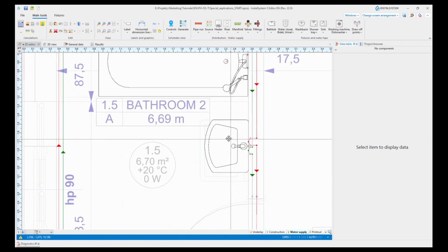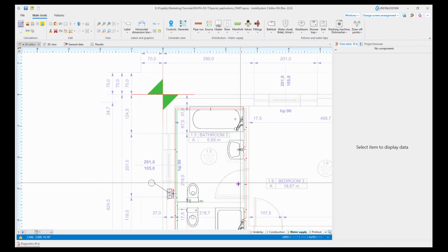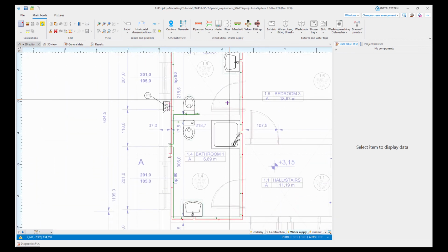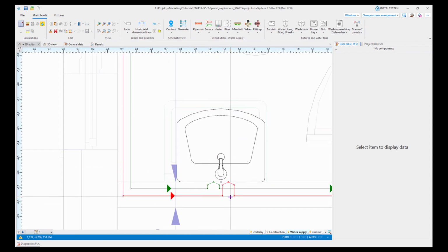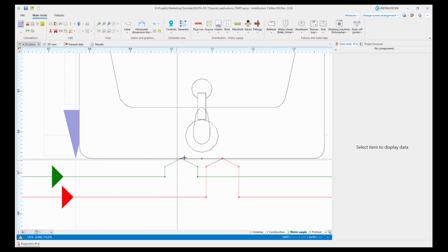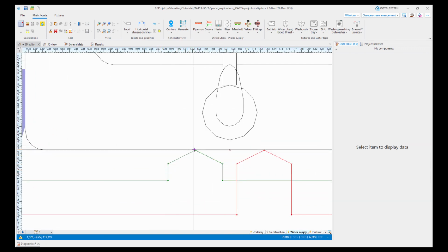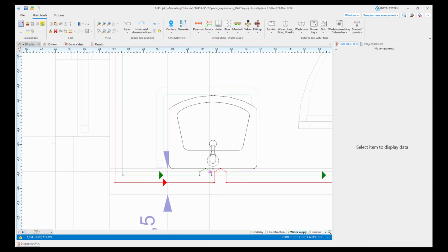So if any of these faucets is opened, we have some circulation of the water in the ring. And it provides the proper quality of the water in the installation. The number and the length of the pipes without the water flow is limited or just eliminated.